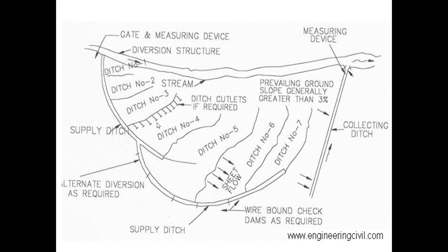In the lateral ditch pattern, the water from the stream is diverted to the feeder canal or ditch from which smaller ditches are made at right angles. In the dendritic pattern, the water from the stream is diverted from the main channel to a series of smaller ditches which spread in a dendritic or tree-like pattern. In the third pattern, the contour pattern, the ditches are excavated following the ground surface contour of the area. When the ditch comes closer to the stream, a switchback is made, and thus the ditch is made to meander back and forth to traverse the spread repeatedly.